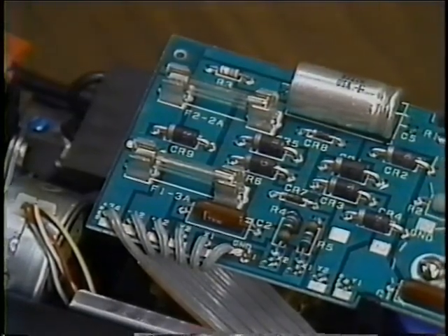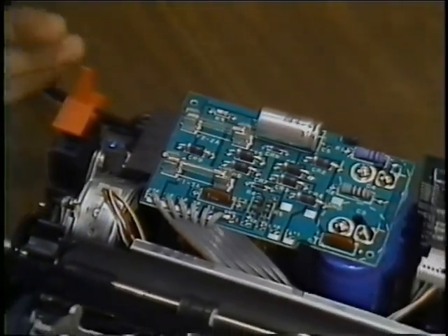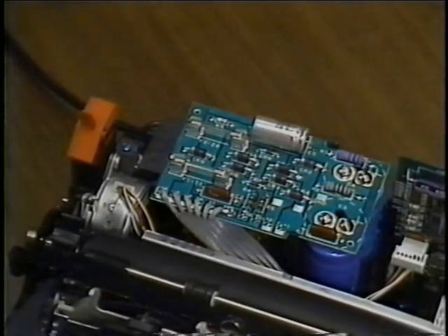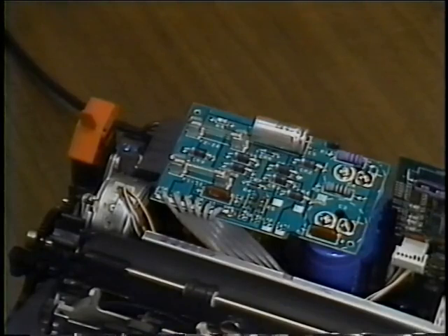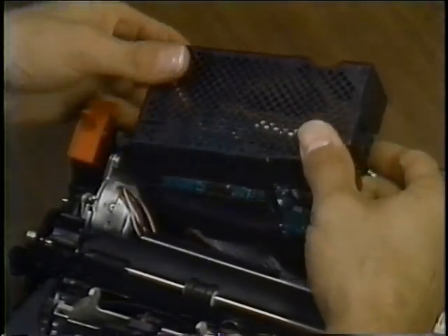If the fuse is bad, you will read voltage on one side only. Always be sure the power has been off for at least 2 minutes before installing the power supply fuses. After checking the fuses, be sure to install the power supply cover.